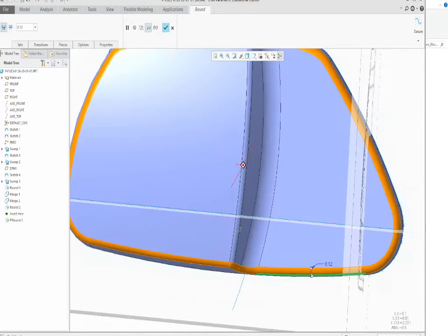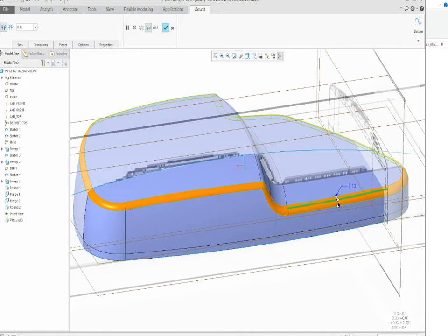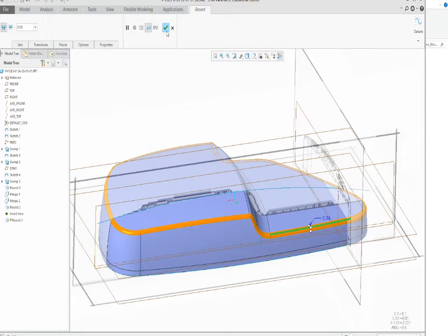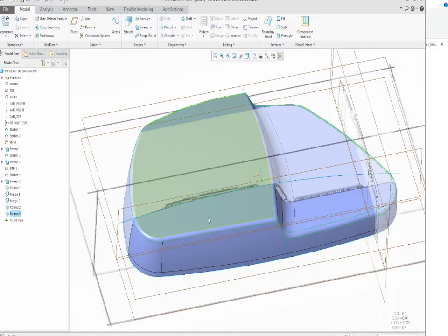And that one looks pretty good. To me, that looks nice for the design. Alright. I could go a little bit smaller if I wanted to. So let's even go a 90. What's nice is you can see the arch happen here and it doesn't sharpen. So that makes it nice for a ball end mill to travel on the design. Now, once we've got that into place, I'll hit save.